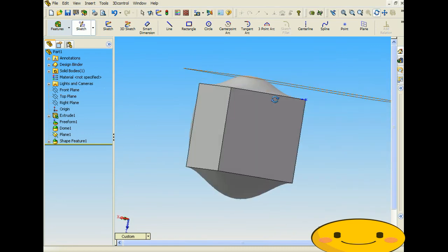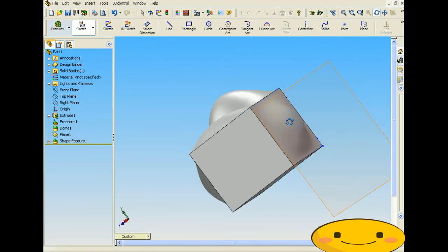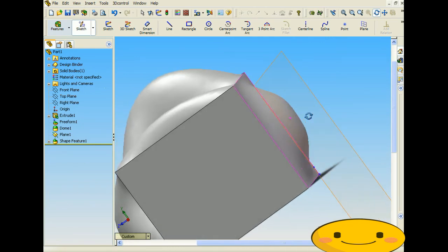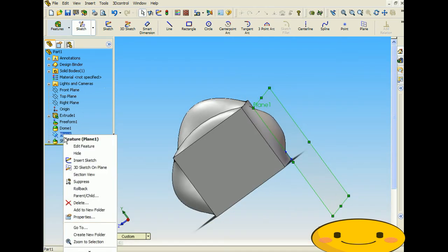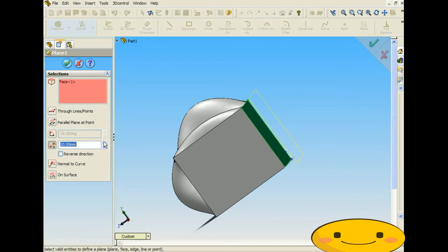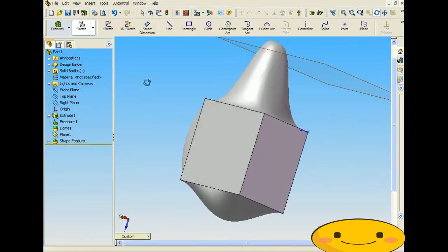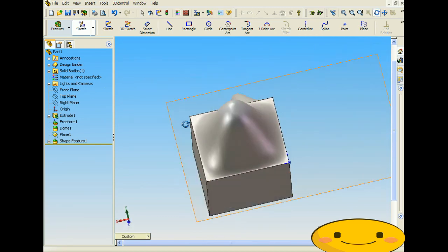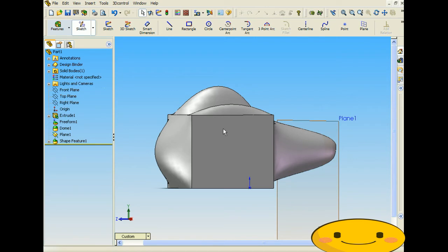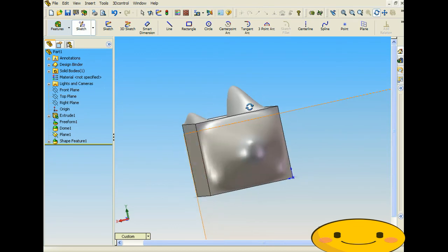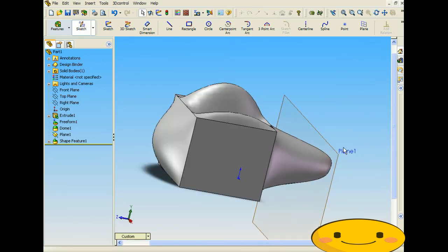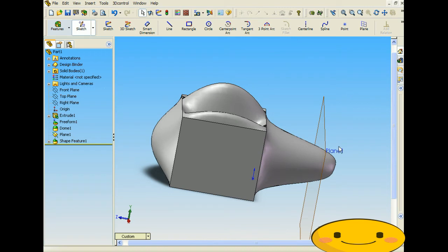And you can see that we've sort of made a dome down there while using the circle. Now what's cool about this too is if we offset this plane some more, let's click Edit Feature, and let's say that we want to offset it to 50, click OK. Our shape follows the sketch that we just made, and it's going to keep moving around with it. So you're able to make a sketch, and you're able to make kind of like a form or a shape come out of the object, and it's going to be representative of that sketch that you've made. So as you can see, pulling the plane front and back, the shape is going to follow it from front to back. It's going to move around with it.